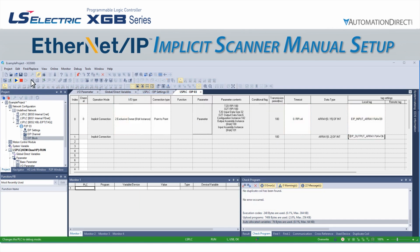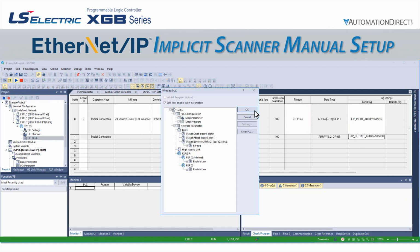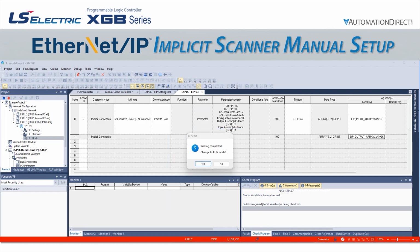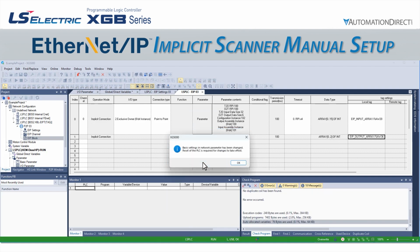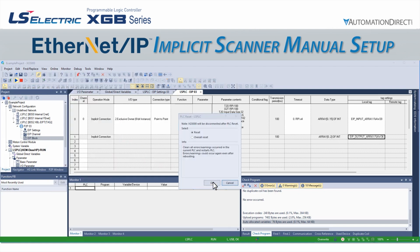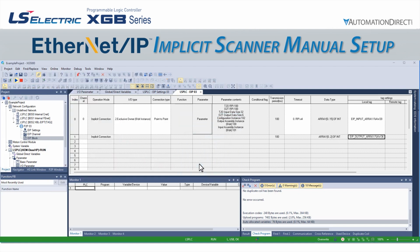Let's write this to the PLC. Once complete, we will have to reset the PLC as we have made changes to the communication settings. We can then reconnect and go into monitor mode.